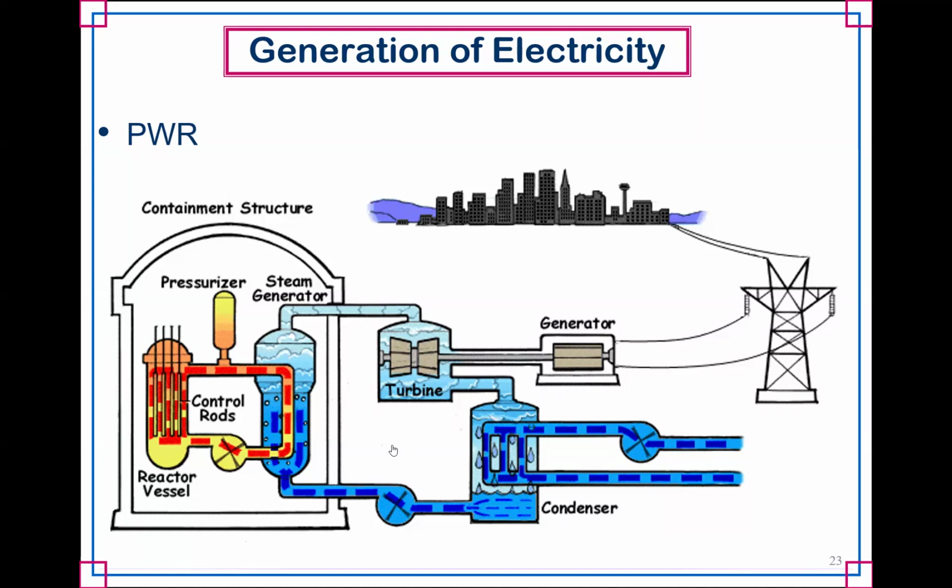The condenser, you have to take that steam all the way back to water. So you have to cool it down a little bit. And so that's why we need those cooling towers that we saw earlier. Then you have a condensate pump that sends the water back to the steam generators, and the process rinses and repeats. It's a completely closed loop system.